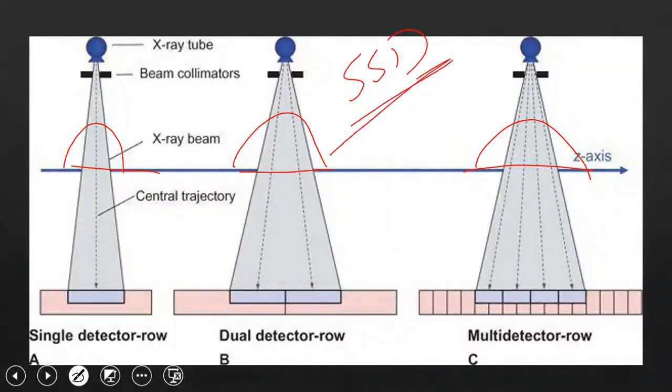When X-rays fall, light photons are emitted, which are received by a photodiode and converted into an electrical signal. The solid state detector has the advantage of high detection efficiency reaching 90%, and high geometric efficiency reaching 80%. You can achieve this in a small size, and you can make it possibly down to 0.5 millimeters, allowing you to create slice thicknesses for images with a small footprint. Of course, this varies from manufacturer to manufacturer.